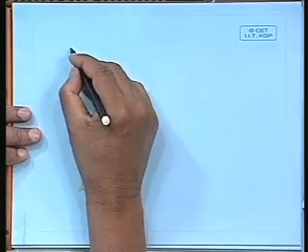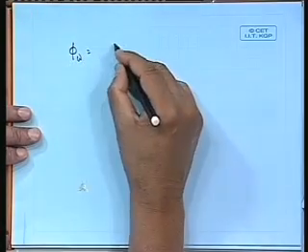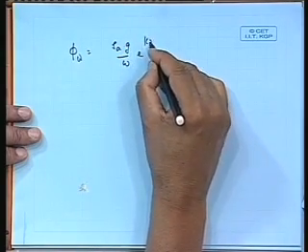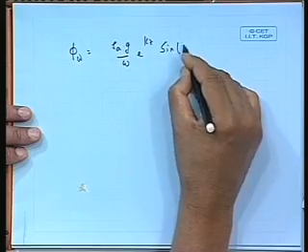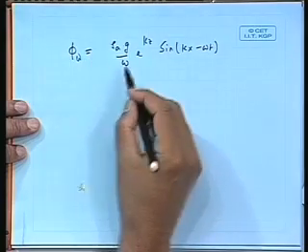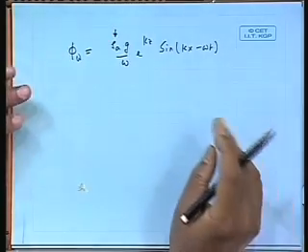Okay, let us now look at other things like velocity. So, we start with this phi wave, which was given as... Now you see that there is an interesting part to be observed here. First of all, you will see that this is proportional to xi a. That means all parameters found in this theory depend on the wave height. If wave amplitude is 1 meter, whatever happens, if it is 2 meter, everything will become twice, 3 meter, everything becomes 3 times. So, it is what is called linearly proportional to amplitude.